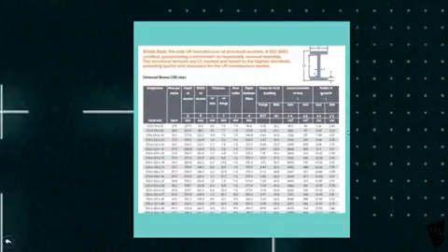This is British steel, so they manufacture. So you've got your dimensions of the I-beam you want here, or as we call it in Britain, a universal beam, a UB. And then you can see the sizes down here, you can see what the weight is per metre run of it, and then it tells you the depth and width of the sections, which are these measurements here, and it'll start telling you some various bits about loads and spans as well.